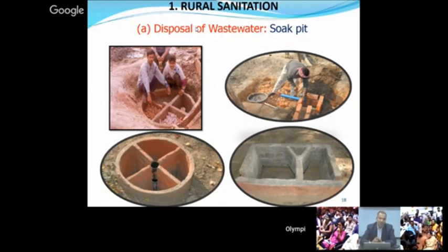stone or brick bats of the bigger size, maybe 5 inch diameter. Then the smaller size, 3 inch size. Then we come to the 1 inch size of stone chips. So these are the three materials used in the three compartments, and the grey water is released from one compartment and it is filtered through this method. And finally, it is released into the ground. So this is a simple way.